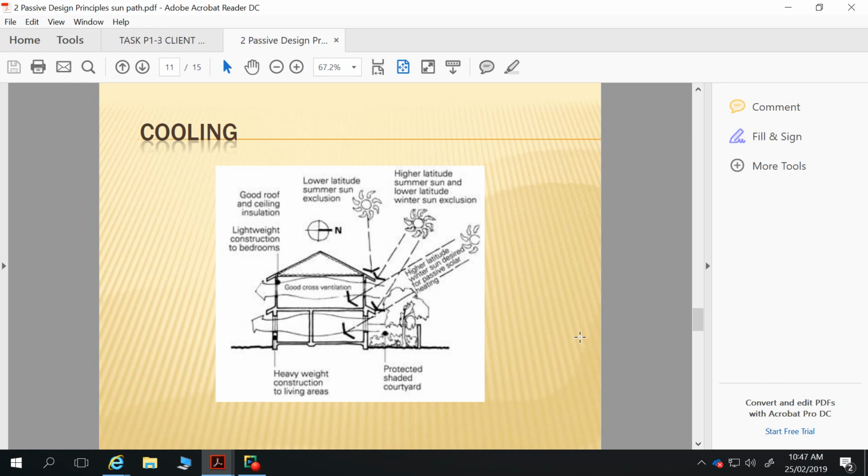It's pretty much southerly, like southwesterlies. Yeah, because that Glenwood Reserve is there. So there's lots of trees down beneath. Trees work like air conditioners. Particularly Australian natives are really good water pumps. They get their roots down, they find water and they suck it out of the soil. That can be certainly very problematic if you're on highly reactive soils and you've got Australian natives right next to your house. They'll suck the moisture out and shrink that clay down. But it's a fantastic thing of free air conditioning.